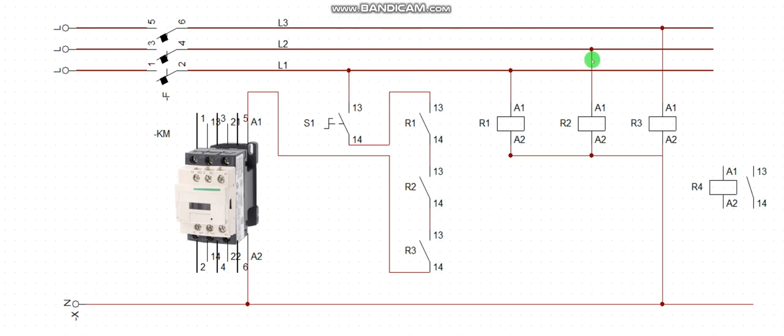Now, this is your supply. This is your MCB. Upon energization of this line, when I have power on three of them, these relays will be energized as well, because each of them takes power from a different phase. All right, this one gets power from here, this one gets from here, and so on, respectively. Then they share a common neutral, and this is my neutral.